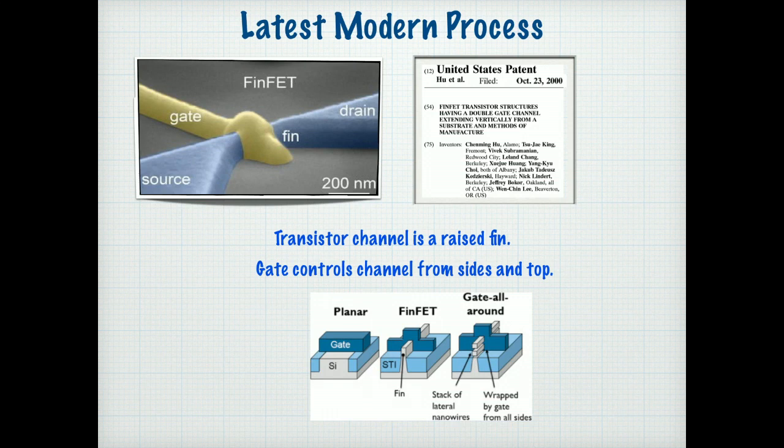As I mentioned early on, this was an idea that was invented here in this building, on this floor, I think. And so this is the so-called FinFET. That's the old planar device. And the newer devices are going to be with the gate wrapping all the way around the channel, not just on three sides. So in planar, the gate is on one side of the channel, in FinFET the gate is on three sides, and in the newer devices the gate will go all the way around, and these have even better electrical properties. That's probably coming up in the next process generation.